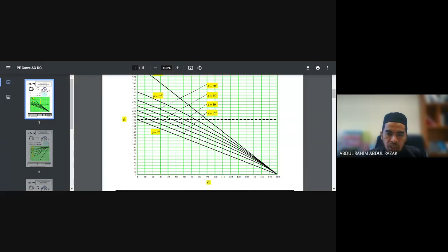Or let's say you have a 20 degree load angle, so you draw your own curve in between here. So when you set alpha at a certain value, what is the expected extinction angle you have here? Or later, if you want an extinction angle of a certain value, what is the expected alpha you need to trigger? Okay.